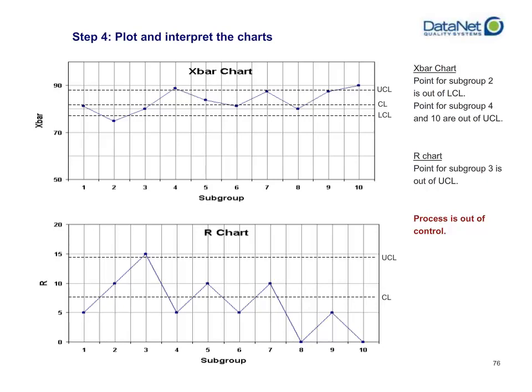You don't really need to plot spec limits when you're doing SPC. That's not the function. The function is first to get you into statistical control, meaning to get you into a state where you are stable and your process is not shifting, which this process clearly is. But afterwards, then you can begin to look at what's going on. Why are you now straddling the upper spec limit?